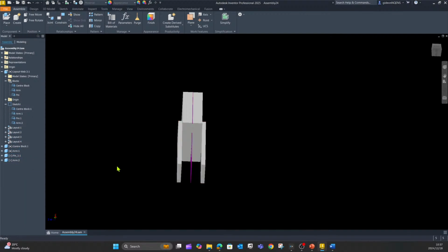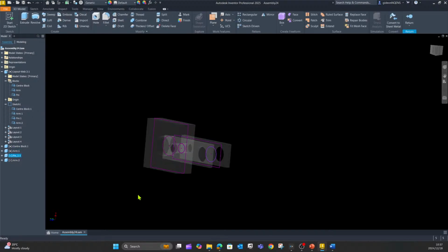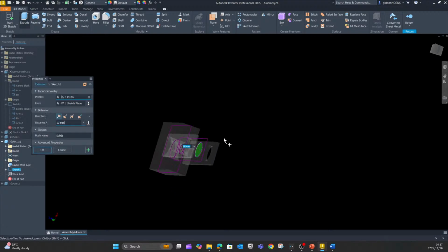It would create the constraints and the different types of constraints, like your mates, your offsets, everything individually as it's drawn by the sketch and driven by the geometry that have been created. Going to go to the pin. I'm going to utilize the extrude in both directions, and I can give it a specific value, let's say 16, just as an example, or let's say 18.